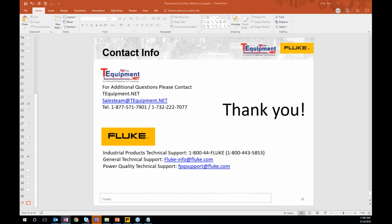And most of the Fluke power quality tools have kind of an easy mode, where if you put it into this mode, it'll set all the limits for you per that standard. And then if there's anything that exceeds that limit, whether you have a rapid voltage change like a transient, or a dip in voltage or current, or if you have harmonics, then it'll visually tell you by alerting you, hey, that bar is red or whatever. If it's green, it's okay. And so that's how you can tell if your power quality is good or bad, is just put it into that easy mode on our tools.